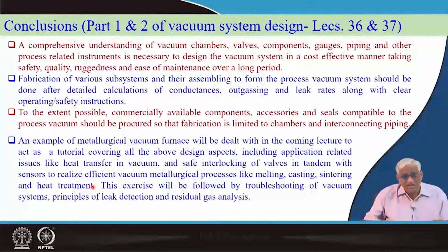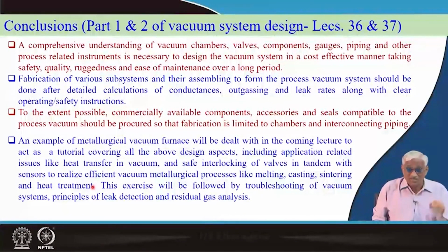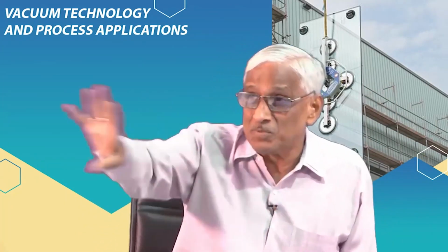They need to be heat treated, but they cannot be heat treated in air. It is a heat treating furnace. Okay. Similarly, casting and melting some alloys, aluminum alloys, etc. That is another aspect of furnace, where oxygen should be less. So, the RGA signature should tell us do not melt now. And similarly, rotating couplings are required from outside to inside, because after melting you have to cast it right in the vacuum, and thermocouples, temperature measurements have to be done parallelly. Everything should be computerized, and a beep signal should come, some alarm should come if something goes wrong.